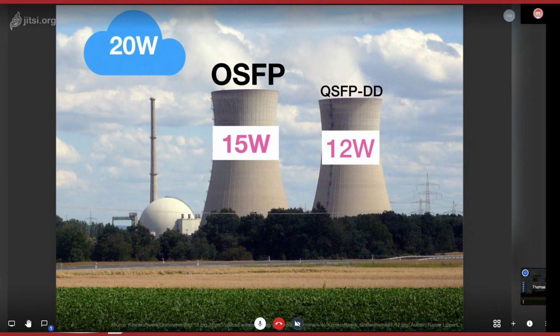I come to those newer things on the next slide, but even this landmark of 15 watts, although it's standardized, isn't enough. We now see movements in the lab environment that we can drive 20 watts in a QSFP-DD. And how does this happen? You might remember those 35 millimeters on the previous slides where I showed the portion which sticks out of your switch.